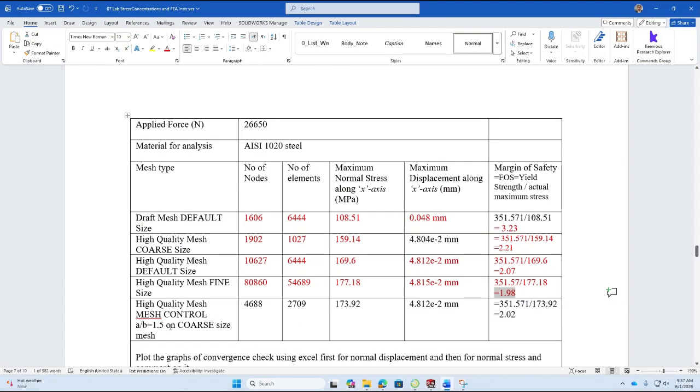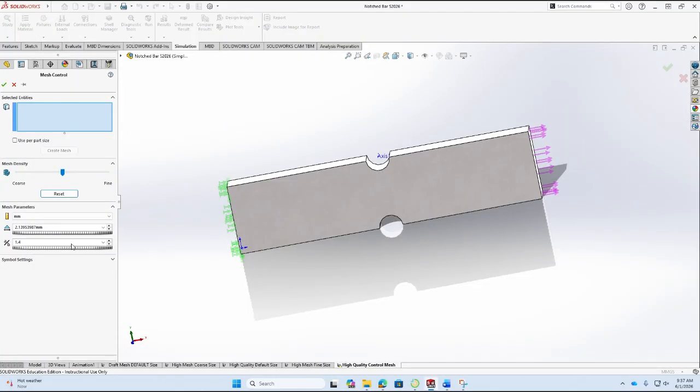And then this ratio determines the transition. So this ratio can be, I have used 1.5 in this case, so I will use the same, but you can play with this ratio to understand how the transition will take place. There is actually a mathematical formula in the book that I have given you, the PDF. It explains how the element size will change from that smallest element size to become the biggest. So it's kind of a ratio. Okay, so you can look at that formula, but right now I'm using the ratio to be 1.5. So it means it will change by that factor of 1.5.